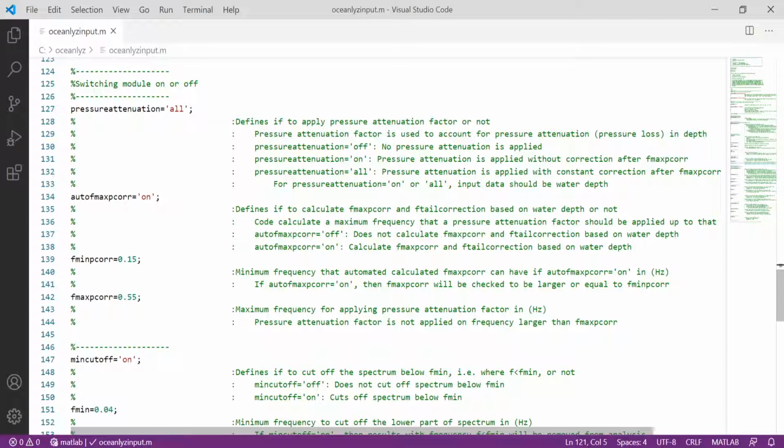So we need this area only. We measure the pressure, and we use the pressure to measure data. And remember, if you use a pressure sensor, the input should be water depths. Remember, the input data should be water depths, because we need the water depths to calculate that energy loss and compensate for it. So it cannot be the water surface elevation, it should be the water depth.